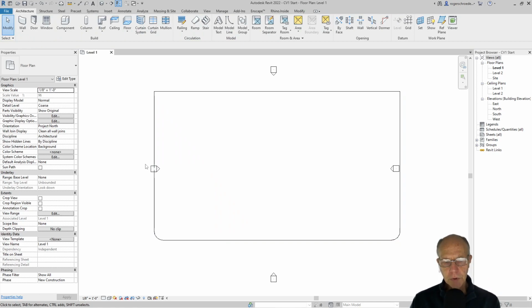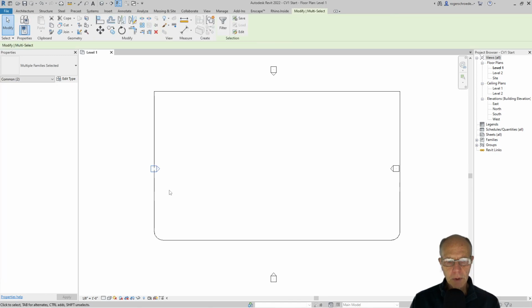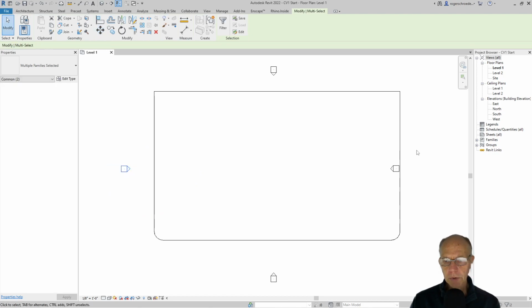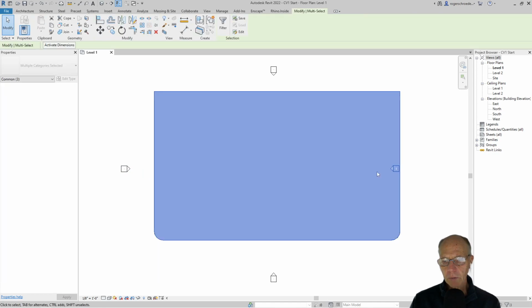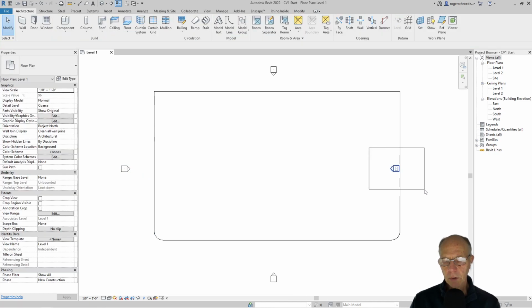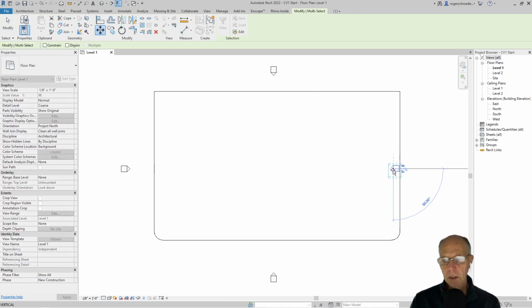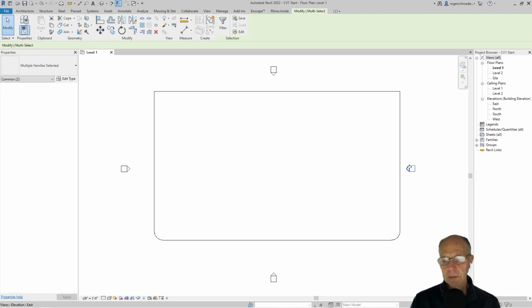These tick marks should be outside of where you want to see your object because these are like cameras that are going to show your elevations. This is not going to be an issue for us in this project, but one of the ways I can do it is just select all of that, grab the move button, and then just pull this back. I want to keep that horizontal marker showing. And I'll do the same thing over here. Oops, I have to go from left to right in order to select that without selecting other things. And then I'll just slide this off.